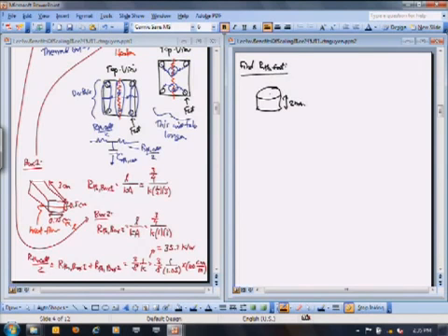And so obviously the things that we need are the length of this thing, and the length of this thing is going to be just this. That's the amount of distance that the heat has to go across to get to ground, which is on this side where the foot is planted on the chassis in this case. This whole thing is still made of glass. And the area, we'll be very interested in the area here. That's going to be pi times r foot squared. Okay? And so, I guess that's L foot.